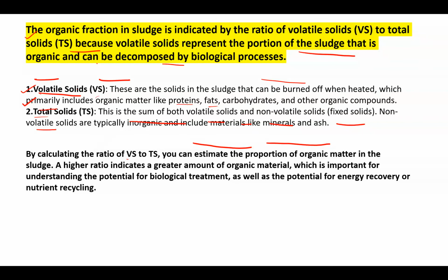So when we take this ratio, volatile solids represent proteins, fats, carbohydrates, and other organic compounds, divided by total solids. When we apply thermal energy, it gets fully burned off and converts into the gaseous state. There are volatile solids and also non-volatile solids.